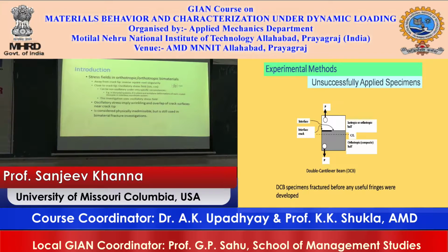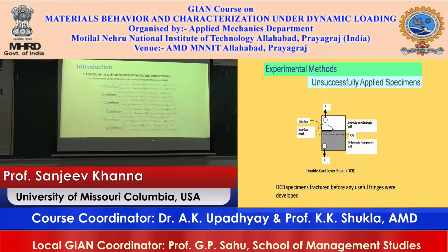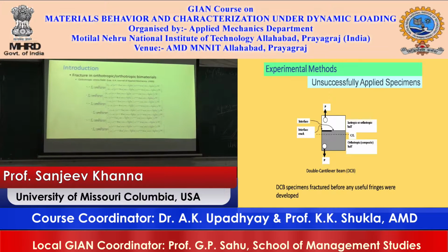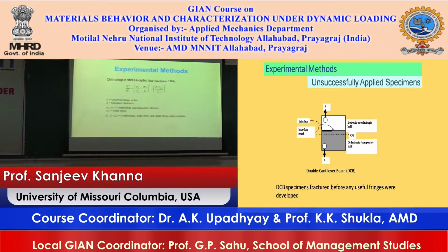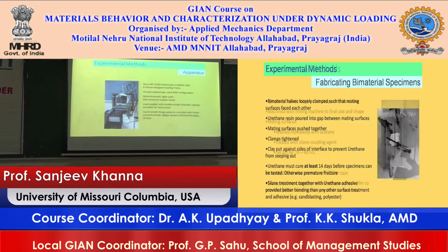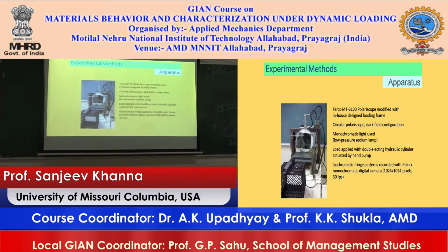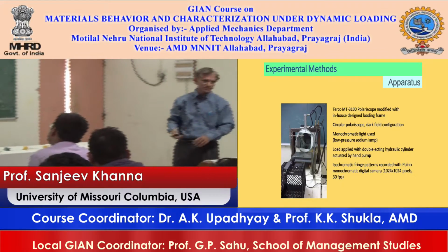I need to find the stress field around the crack tip. And if you can read that, that's the stress field: sigma x, sigma y, tau xy. It has the same series solution we are using again, and we combine it with the stress optic law and do the exact same thing again. You take a lot of points from the field of view around the tip of the crack, but avoid the center portion, a diameter of one thickness. Take points up to a maximum of 4 times the thickness of the sample.